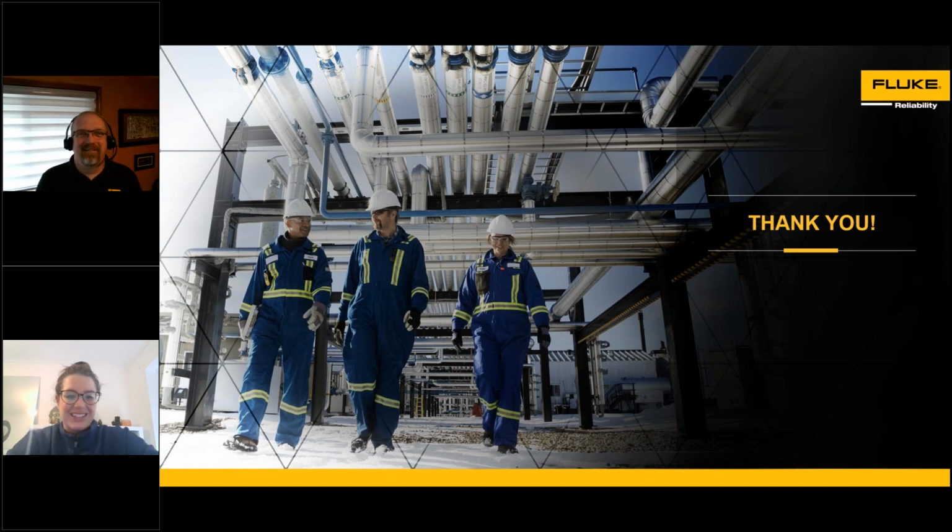No, that's good. And then if we have a wireless condition monitoring system, do we still need an on-site analyst? So yes and no. Wireless and remote condition monitoring can detect failures in the vibration data, right? One of the things that they can't do is go out there and actually observe the machine condition.